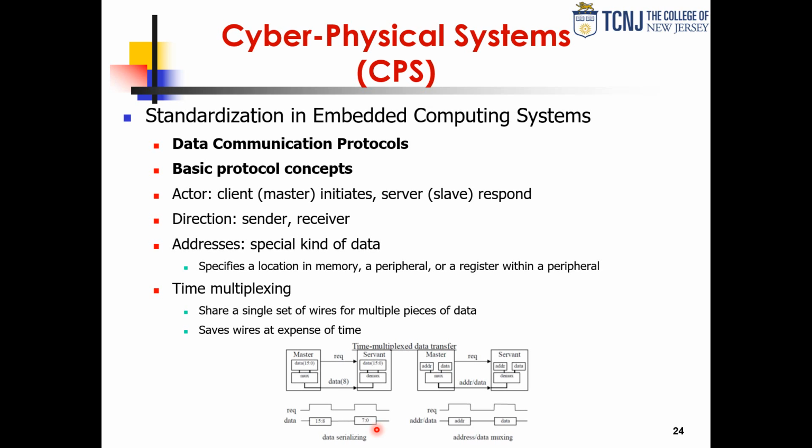You could do that on the same lines, in this case, and let's say that you have 16 bits of data, and you only have 8 wires, so you may be sending 2 chunks of data, but now you have 24 bits of address. So maybe your scheme looks like address, data.